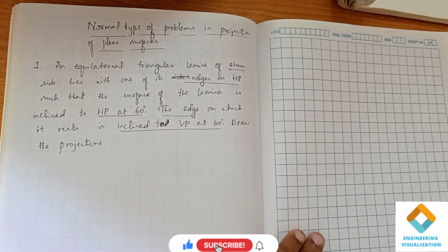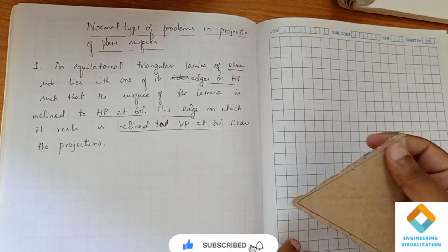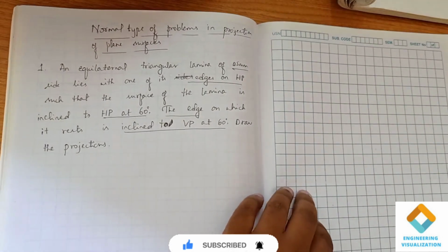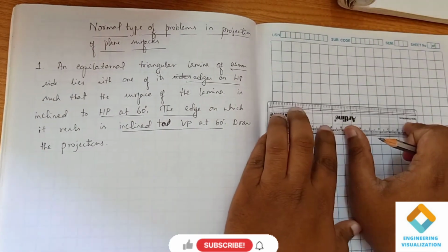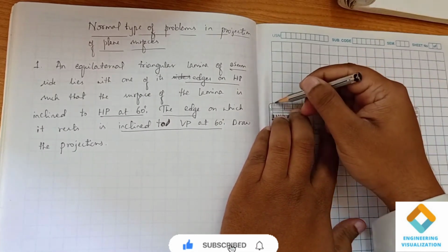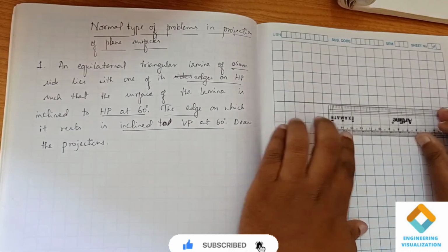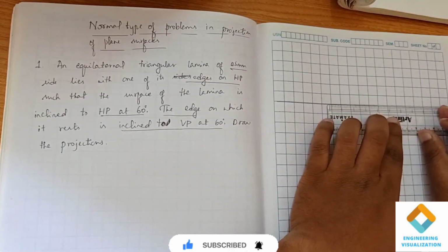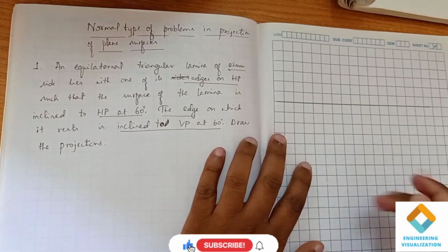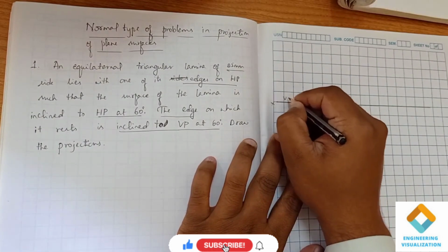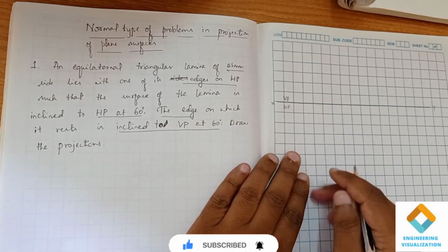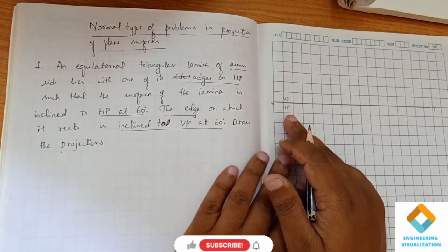So if I am showing the solution here, we have to proceed. I'll be drawing the first position. We know how to construct the first position, right? First I'm drawing an XY line, because in this projection of planes we are going to use only the first quadrant. Okay, remember it. We are not using the second, third and fourth quadrant. We are restricting our problems from projection of planes only to the first quadrant. That's why VP, HP.